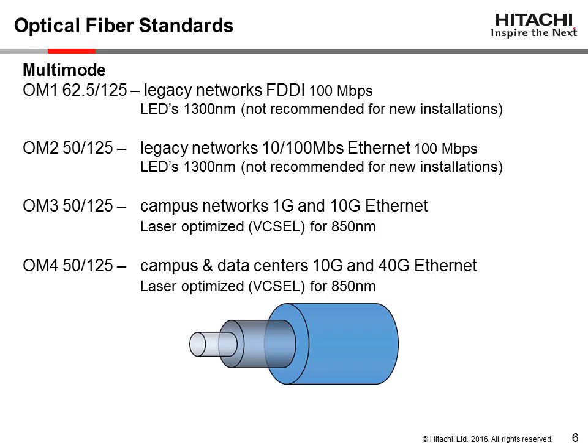Looking at the 4 multimode optical fiber standards and application examples, OM1 and OM2 fibers represent solutions for older generation legacy systems such as FDDI, Fiber Distributed Data Interface, and Fast Ethernet 10/100 that are still operating today and designed for data rates up to 100 megabits per second. These fibers may also be used in industrial process control applications that typically operate at lower data rates and want to take advantage of fiber's immunity to electrical interference.